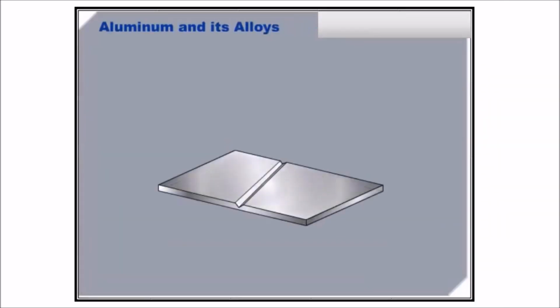Aluminum alloys have a very tenacious oxide film on their surfaces, which forms very rapidly when the bare aluminum is exposed to air, and these oxide films give protection in corrosive environments. These same oxides on the surface interfere with the joining processes.